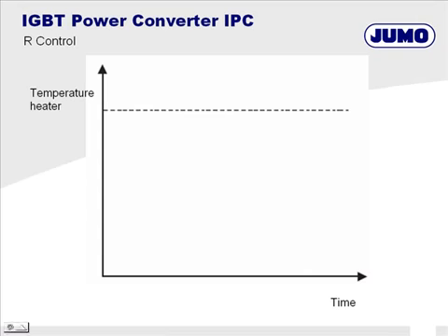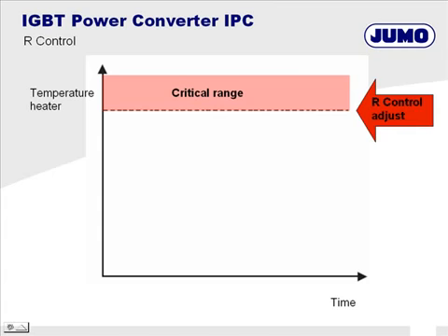A very high heater temperature reduces the running life of the heaters or can even destroy them. The power converter can measure the temperature via the element resistance and reduces the power output when the maximum temperature has been reached. The heaters are not stressed by very high temperatures and consequently they are not destroyed.